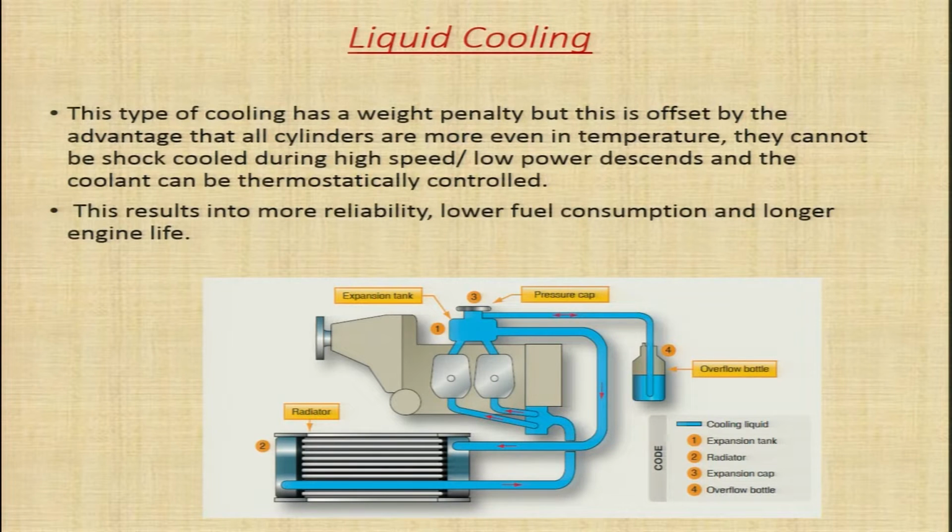But this penalty is offset by the advantage that all the cylinders are more evenly cooled. They cannot be shock cooled during high speed or low power descents, as was the case with air cooling, and the coolant can be thermostatically controlled. So the coolant is thermostatically controlled, you do not get shock cooling, and all the cylinders are evenly cooled.